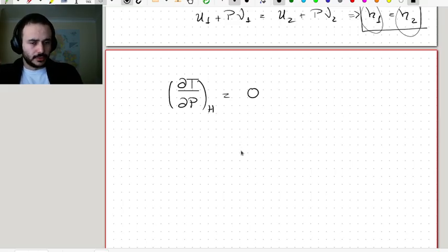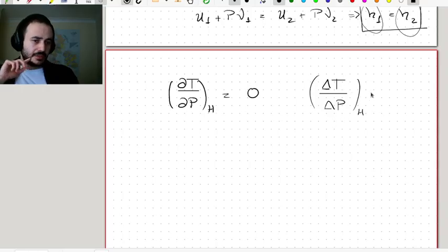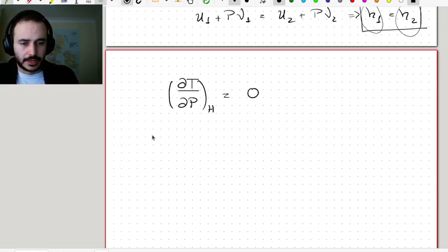That's what Joule arrived at. So this is the conclusion that you arrived at from measuring the temperature on the two sides. Because you know, what's the change in temperature in an isenthalpic process, which is steady flow, thermally insulated, when the pressure changes by some amount? What is this, in the infinitesimal limit? But this is zero. This is what Joule was finding.